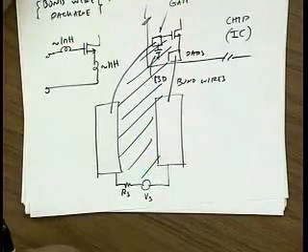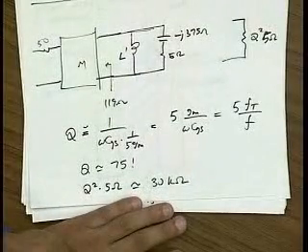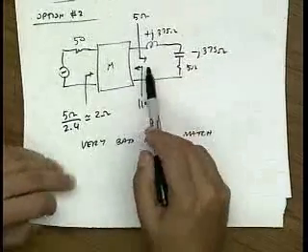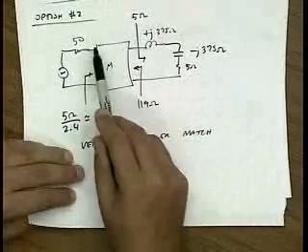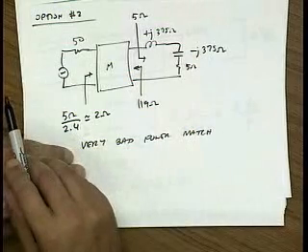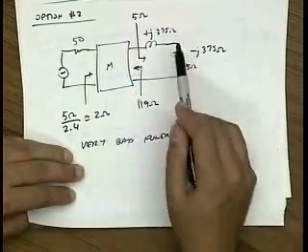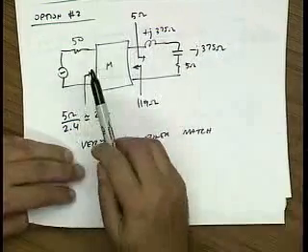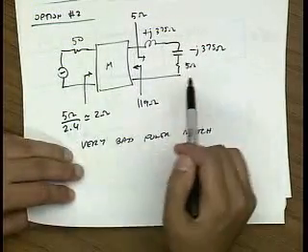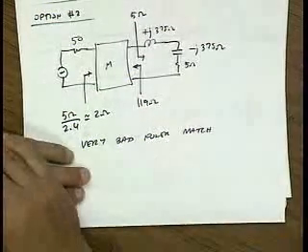Sure. Can you combine option 2 and option 3 by inserting a small series inductor with a capacitor and then putting a big inductor in parallel? Yeah, so basically you could do a multi-stage, right? So over here, I can have another matching network to try to match this up. So this is 5 ohms, and then I have another matching network to get to 50 ohms. But the problem is that all these components are in front of your amplifier, and any insertion loss adds dB for dB to your noise figure. So all of a sudden you have this complicated matching network, and instead of getting a noise figure of 1 dB, you're going to get a noise figure of 5 dB. Okay, I'm exaggerating, but it's going to hurt you.